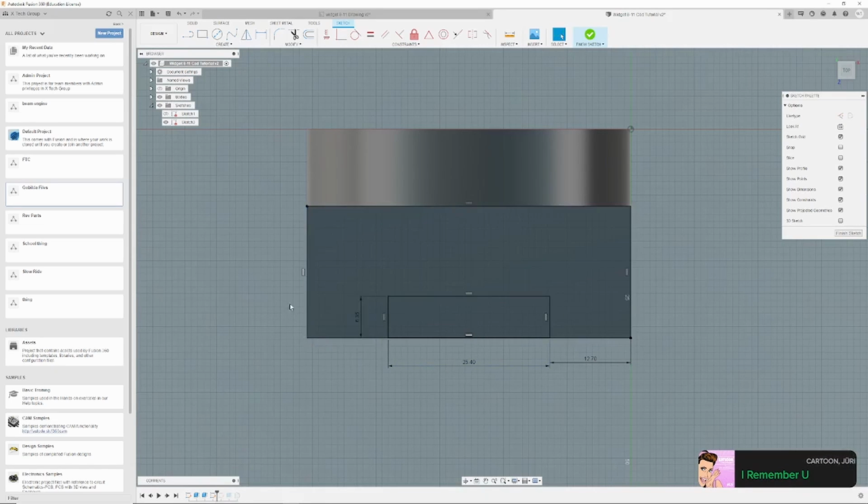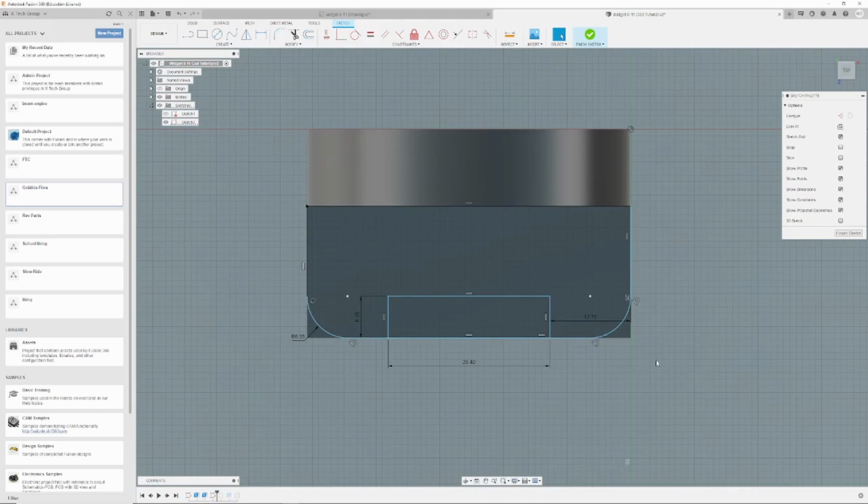And then, instead of using the fillet tool on the model itself, we can come up here and fillet the sketch. Click these two corners, 6.35, 6.35, and now everything turns blue because we lost our dimension to the edge, but that's alright. Your lines don't have to be black in order to use them.